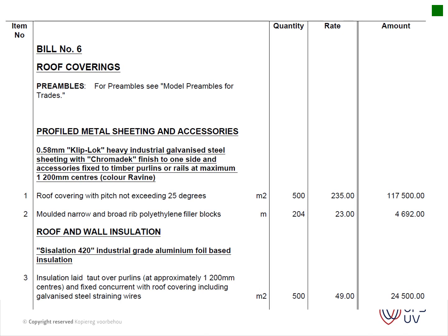Then our bills of quantities. Very important to note is that we've got bills of quantities. Our bills of quantities comprise many bills divided into trades. So now you've got your trade of earthworks, your trade of masonry, carpentry, which includes your roof construction. Except if it's steel construction, then it will fall underneath structural steel, for instance. So the subcontractor would be a steel worker.